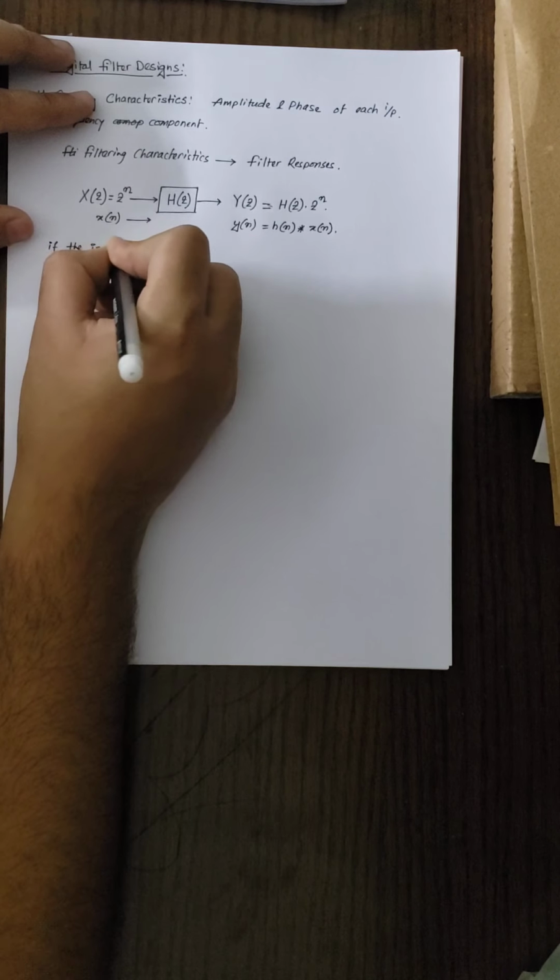So before going into the derivation, it must be mentioned that the derivation that will be shown is only true for stable systems and is whatsoever not true for marginally stable or unstable systems. So here on forward, all h of z must lie within the ROC of z.